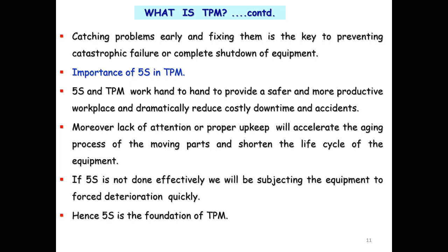If proper attention is not given in upkeeping the equipment, that is, 5S is not done properly, and normal day-to-day maintenance activities are not carried out as per schedule, then the aging process of the moving and rotating parts in the equipment will accelerate due to dust and other contamination, which will shorten its life cycle time. In other words, you will be subjecting your equipment to forced deterioration instead of normal deterioration. Please note that 5S is very important and a tool and is the foundation of TPM.